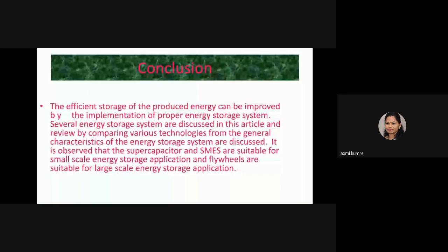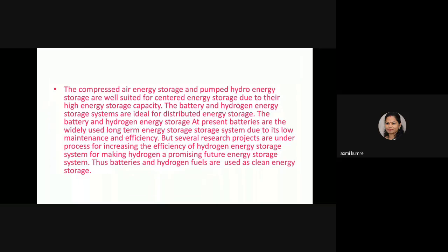It is observed that supercapacitor and SMES are suitable for small scale energy storage applications and flywheels are suitable for large energy storage applications. The compressed air energy storage and pump hydro energy storage are well suited for central energy storage due to their high energy storage capacity. The battery and hydrogen energy storage systems are ideal for distributed energy storage. The battery and hydrogen are the best.